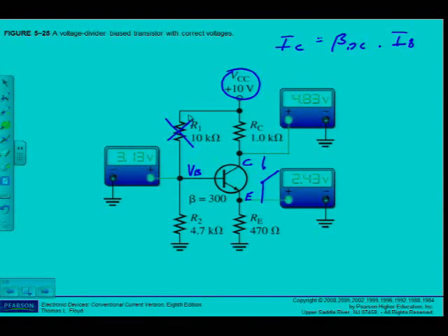So it could mean that the transistor was biased into saturation, but I want to use it for linear amplification. So the design that I've done wasn't designed that way, so there must have been something wrong. So most probably R1 is open. So let's see what they say further there in the textbook.